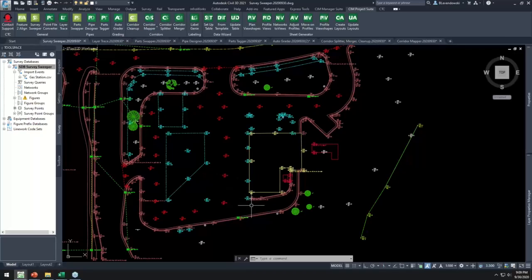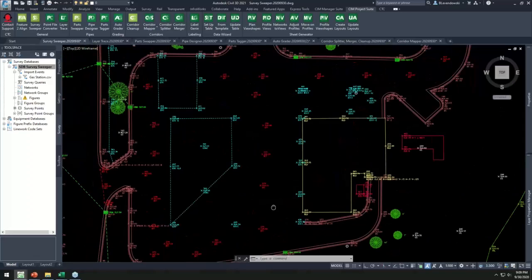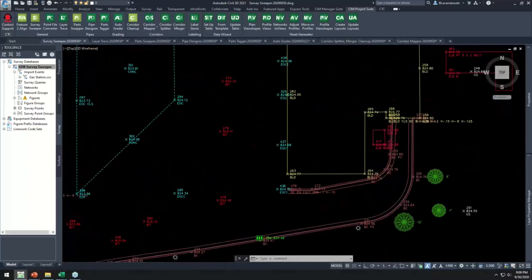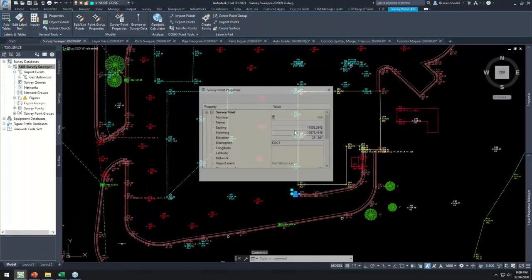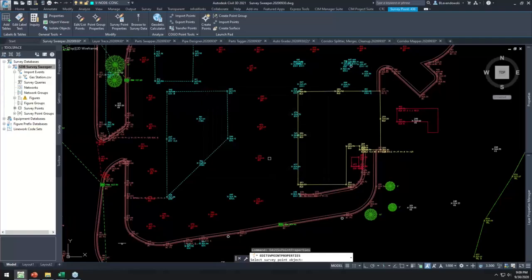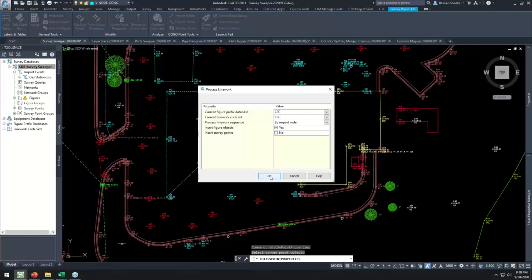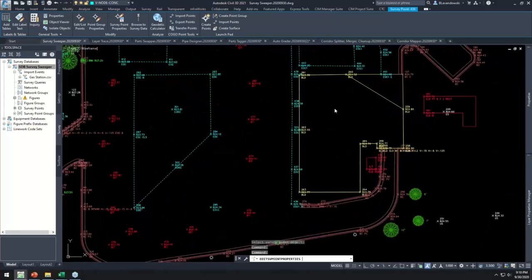If you use survey databases, you know how tedious and kind of clumsy they can be. They're great in that they generate automatic line work for you from your topo surveys. But what about when you do things like this? What's real handy is to be able to fix coding mistakes in your survey codes. For example, I forgot a B code here. If I go ahead and update my line work so that it now draws that back of curve geometry, that's real handy.